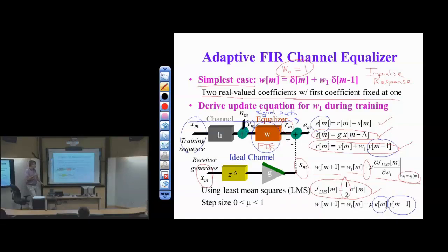Now, beyond the computational side, the least squares method has another downside. We don't have the least squares method here in the slides, but in the book, the least squares method gives you the average equalizer over the training sequence. It doesn't track the channel over the training sequence. So when the training sequence is finished, the least squares equalizer gave you the average case, but it doesn't tell you where the channel is right now. That average case equalizer may not be very good, given the current channel.